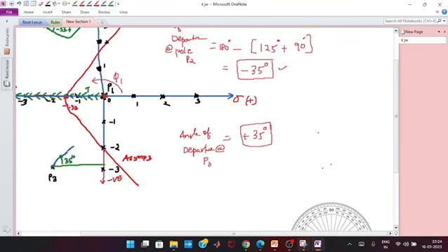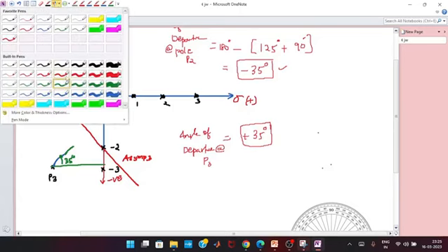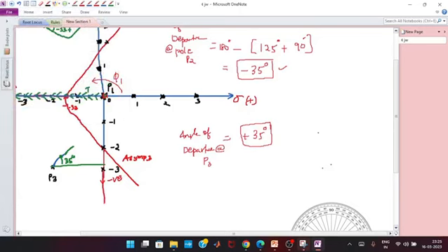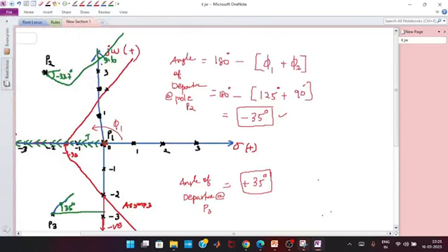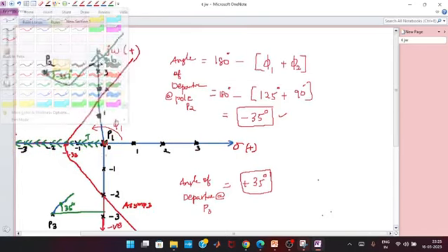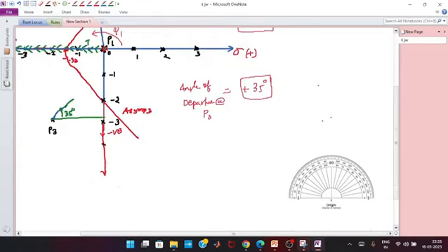Similarly, this will also be like this, right? After it reaches a certain point, it should be parallel to your asymptotes, right? At which point it is intersecting, obviously we know, that is nothing but the crossing point. Now tell me what is the crossing point? If it is 3.6 here, the opposite value is minus j 3.6. The value could be around here because this could be minus 4.